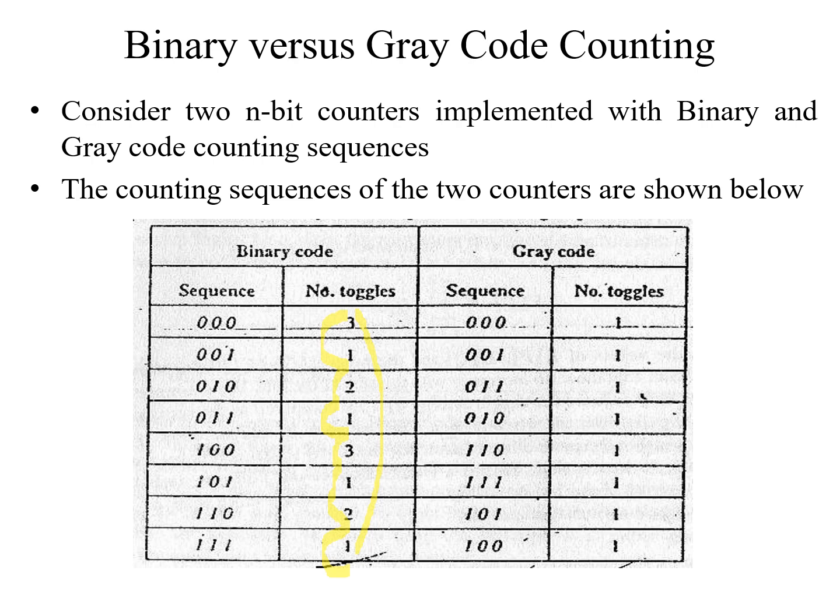But if you take the gray code, only 1 bit changes as the sequence goes from 0 to 1, 1 to 3, 3 to 2, 2 to 6, 6 to 7, 7 to 5, 5 to 4. So this is the binary coding way to design the 3-bit counter, and this is the gray code technique. The power can be minimized by using the gray code counting design.